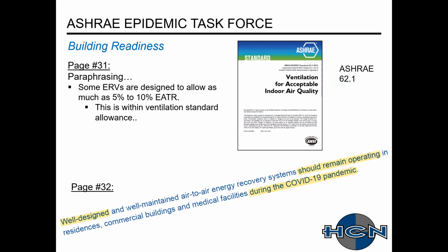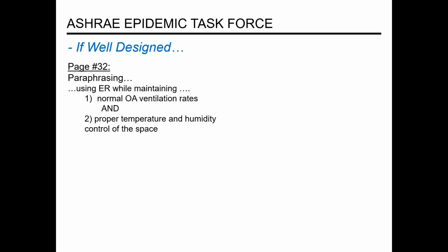So once again, we want to continue to operate our energy recovery system. Why do we want to do that? Well, if the energy recovery system has been well designed, it will maintain normal outside air ventilation rates, and it will also maintain proper temperature and humidity control of the space. This is similar in concept to, but we'll end up maintaining better health and combating infectious aerosols.